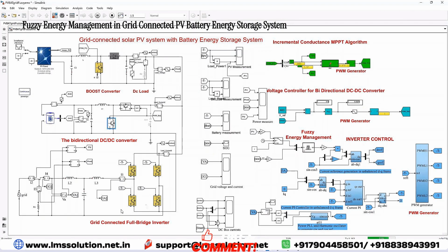Next one is you need to control this inverter. For controlling this inverter, here we are using a fuzzy logic based energy management system. The two inputs are the PV power and the SOC of the battery.